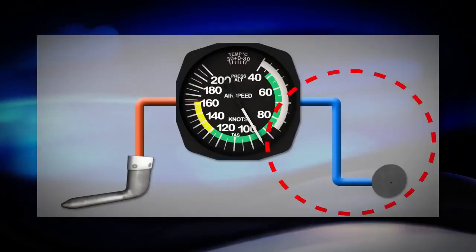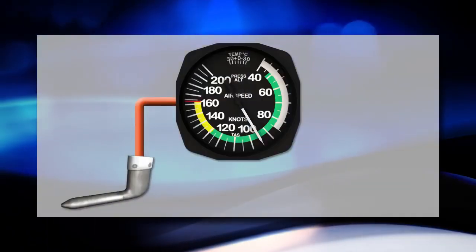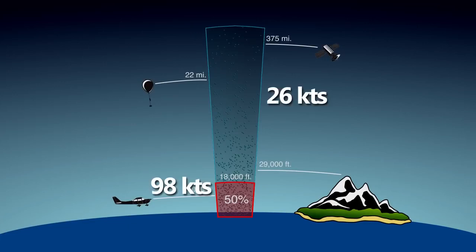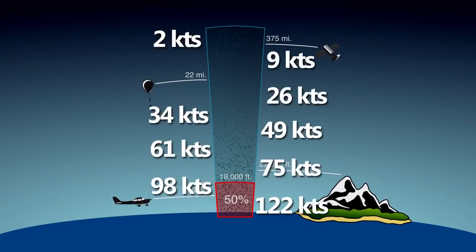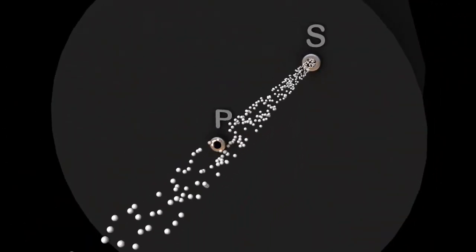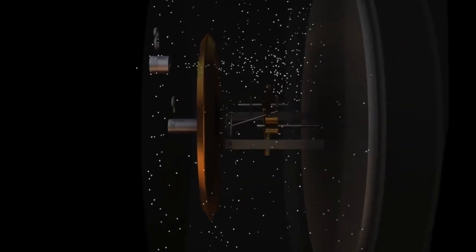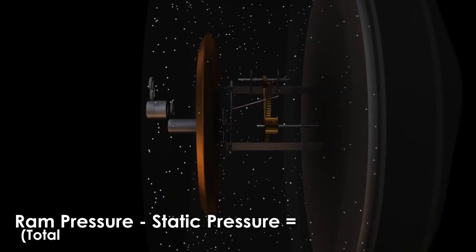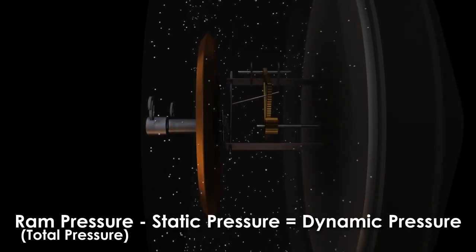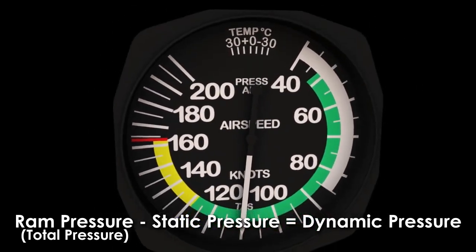But what about the static port, you ask? Well, remember how the pressure of the atmosphere changes with altitude? Well, if this wasn't taken into account, then the airspeed would indicate different speeds at different altitudes, even if the plane was actually going the same speed. To fix this, the static port connects and fills the case surrounding the diaphragm with static air. This will subtract out the static air pressure that the pitot tube captured and only allow for the dynamic pressure to be read on the instrument. This keeps the airspeed indicator reading the correct values no matter what the altitude of the airplane is.